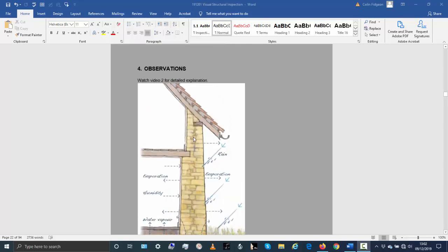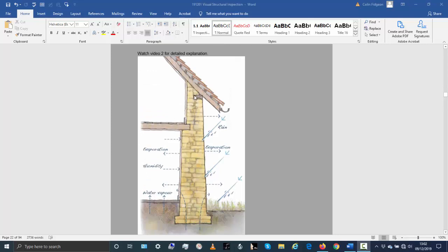So first of all, up until 1940 in Ireland anyway, most buildings might have been built with a solid stone wall like this, very thick wall. And these walls were not built with cement. That's the key difference. They didn't use cement, they used a lime render, and oftentimes lime was just mixed with clay to make a very soft mortar.